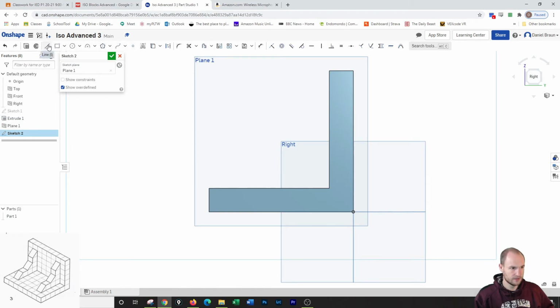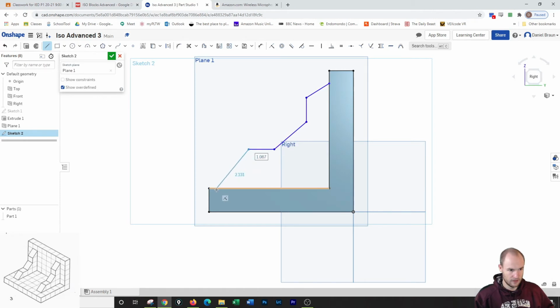And when making a sketch on this plane, hopefully, now you see it does not touch the previous face. So I want to use this tool right here called project. So it projects all of that. So now I can come in here and I can actually draw what I want to draw, which is a roughed out version of what this shape should look like. All right.